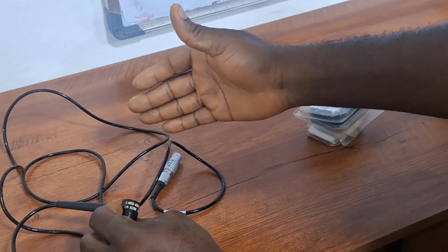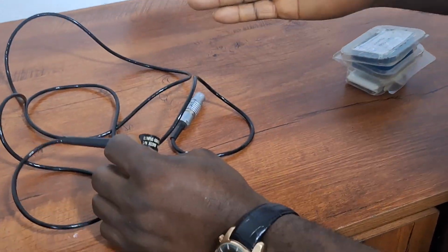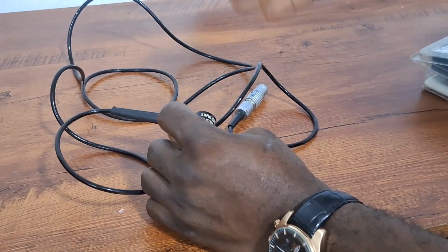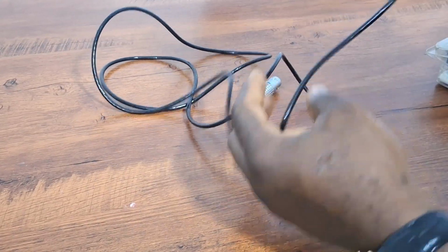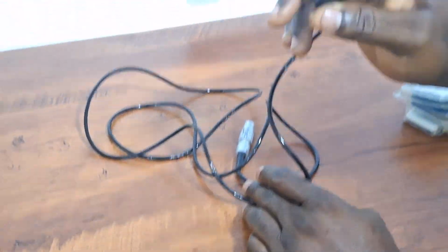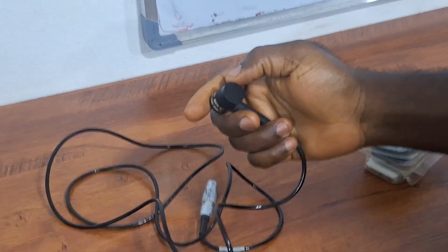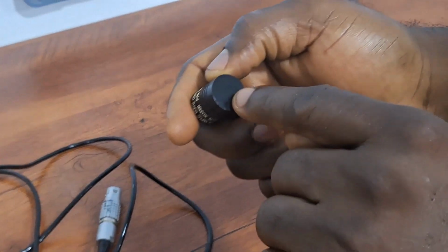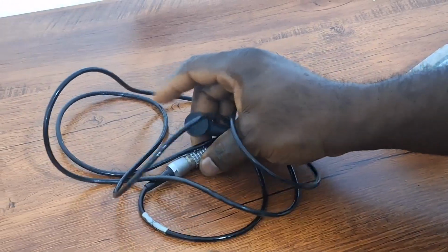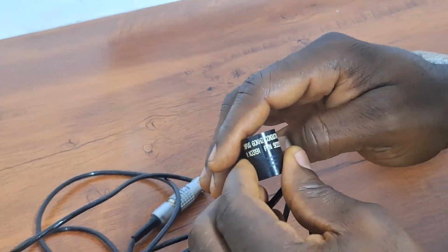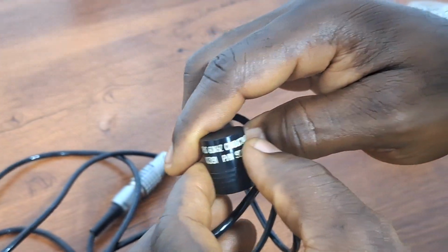So it's not for flaw detection, which is the determination of cracks and any in-service defect. This also is not a surface probe, so do not use it as a surface probe. You can see the coil at the center for conductivity check, so not a surface probe. It is clearly written here, conductivity. Do not use it for surface inspection.